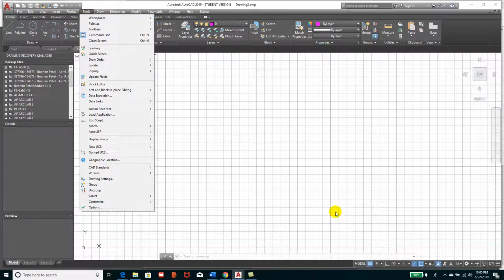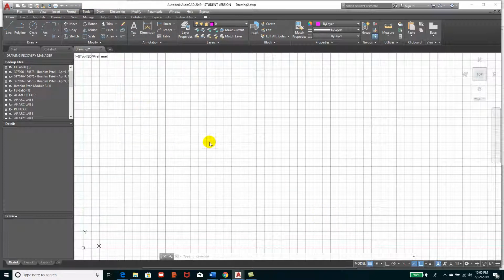The other thing I'm going to do, I'm going to hit escape here to get rid of that menu, is check these glyphs down here. My grid mode is on. This mode right here, object snap tracking, we'll leave that on. OSnap we'll leave on. And then annotation objects, we'll leave that alone, but we won't be using it.